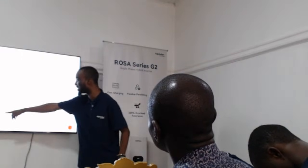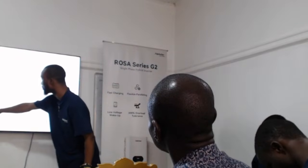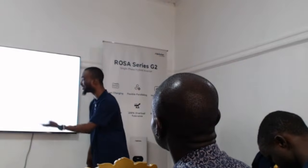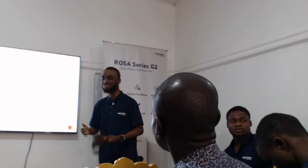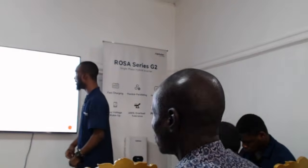And this is for your generator. This is where you can set the charging power for your generator. What power do you want to use your generator to charge your battery? Maximum generator charging power, default rated power, you can set it. Let's say 4 kilowatts, whatever kilowatt power you want your generator to charge your battery. And you can set generator startup SOC. Like I said, this is for smart generator. So you can set what particular percentage of the battery you want the generator to come and start charging your battery, and what particular SOC you want the generator to stop charging your battery.